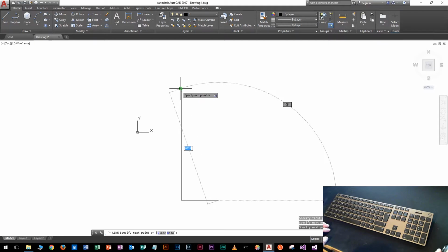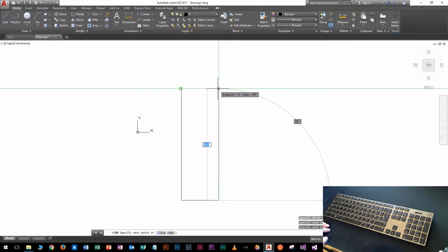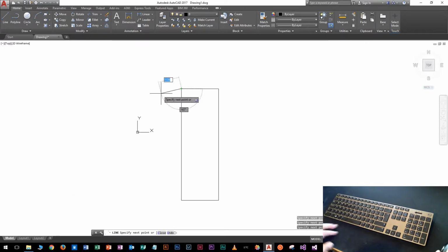Now at this point I can just hover over that first corner and I get a green square, which means that it's snapped to that point. I haven't clicked anything yet, just hovered over it, and if I pull to the right I get a green dotted line, which means that everything is straight. Once I get both lines I know that it is perpendicular, and I can then come over and do a fourth click over here, and press escape or spacebar to finish drawing that line. And that is the outside of my stage flat complete.